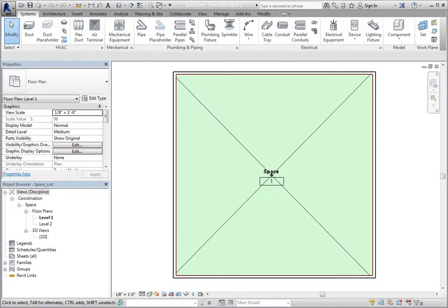In an architectural Revit model, the architect uses a room object. These elements describe a room in a building and have many parameters describing a room that are really of no interest to the MEP design team. The way Revit MEP deals with this is with the space object.